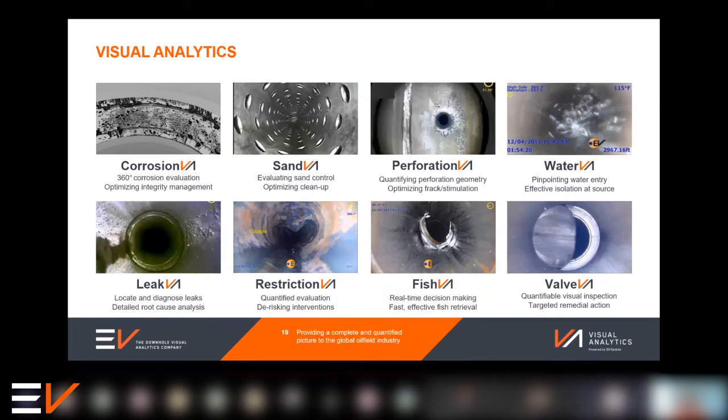In some cases, older designs, it's quite difficult to lock them out with mechanical interventions. What the tractor combination allows you to do is physically deform the sleeve into position, so you can permanently lock it in whichever position you want, open or closed. And usually for safety valves, it's for locking them open so you can install something else.